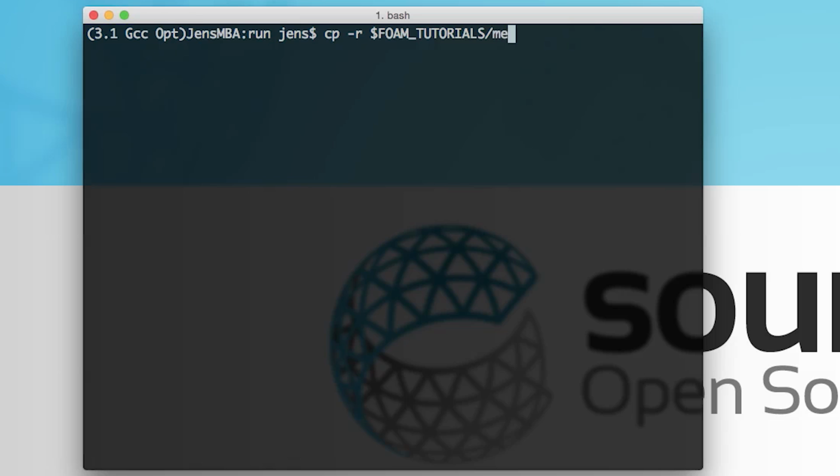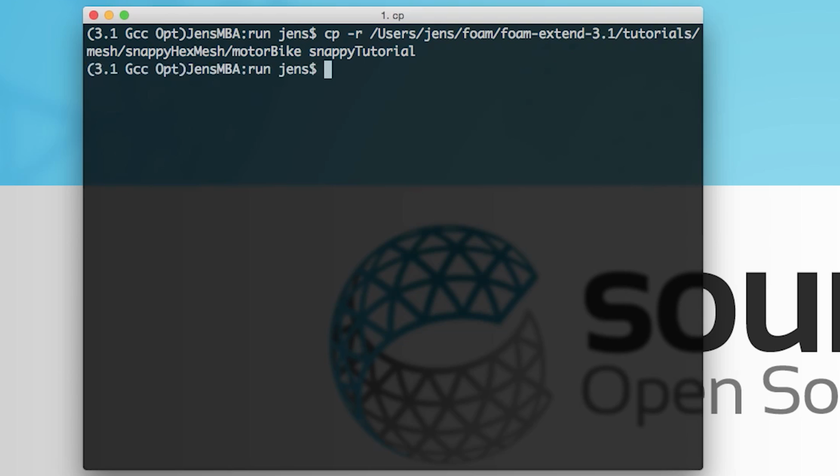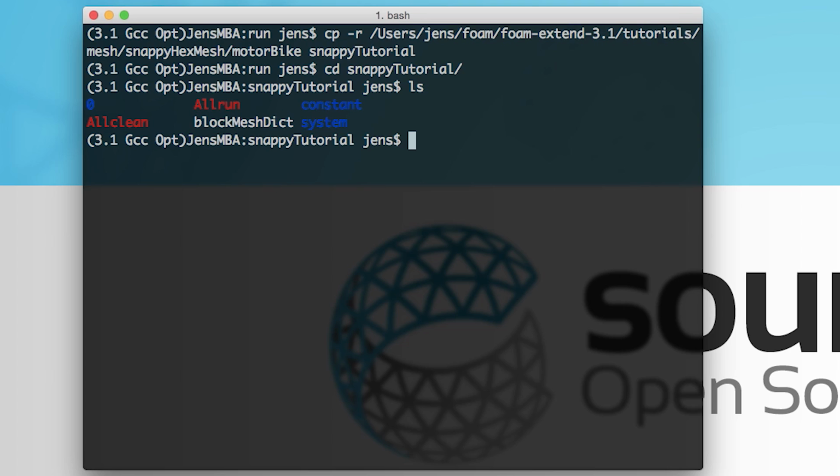As template, I select the motorbike tutorial from the OpenFOAM tutorials. In the tutorials directory, it is located under Mesh, snappyHexMesh, and then motorbike. This tutorial can be copied from the command line using the rather longish copy command that is shown. Please note that I changed the target directory from the current working directory, which would be a dot, to snappy tutorial.